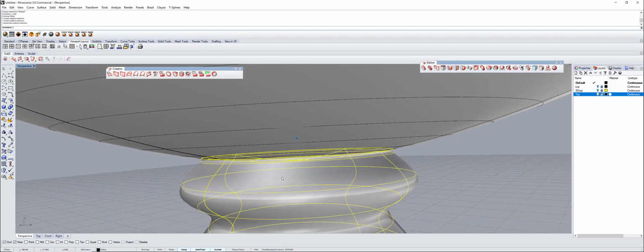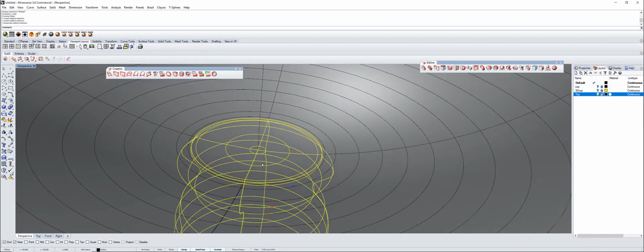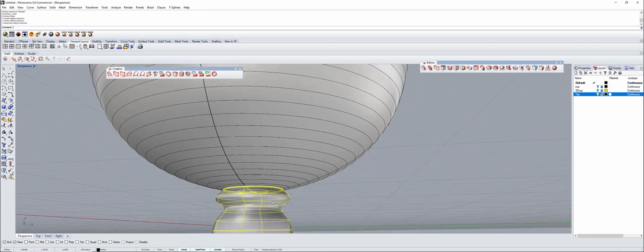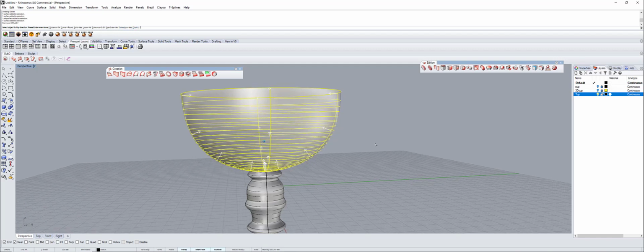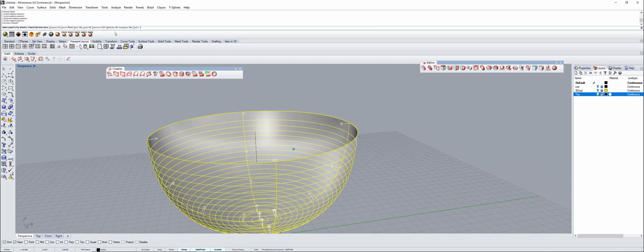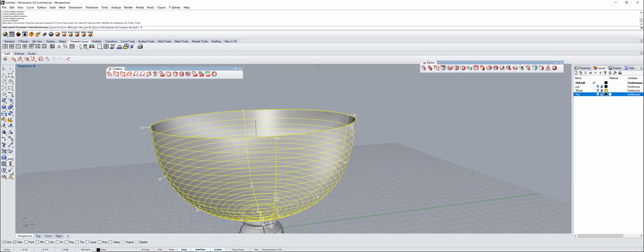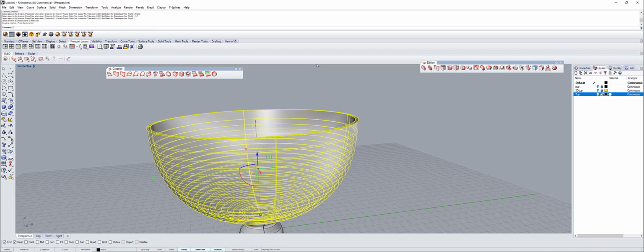Man, this is perfect. Oh no, it's not touching. It didn't pass through. So I'm gonna offset it upside. Okay. So now, what is the magic command? It's offset surface. That's the abbreviation of surfaces. It's like surfing. CRF. Okay, and it's flipping inside, so it's gonna flip it outside. So flip it all, and we're gonna give it 1.2 millimeters. Enter and enter, guys.